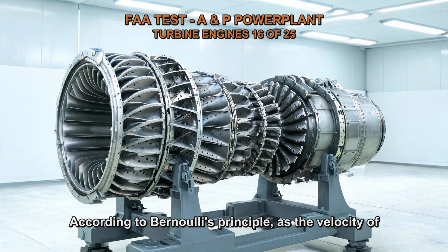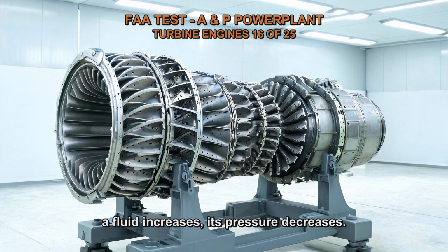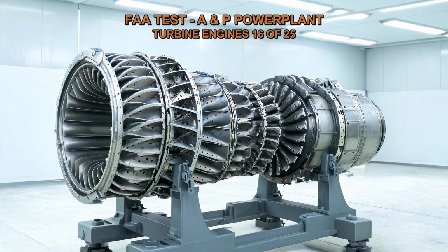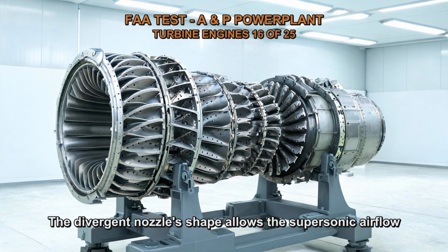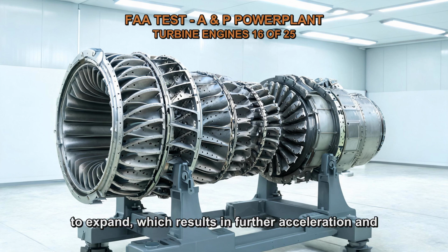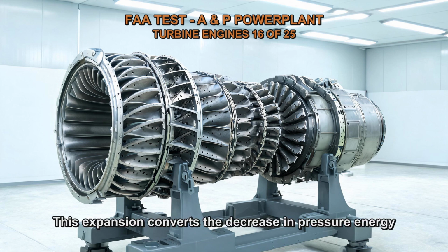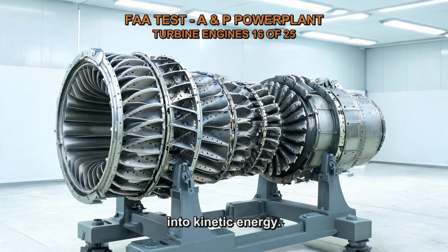According to Bernoulli's principle, as the velocity of a fluid increases, its pressure decreases. In a divergent nozzle, the velocity of the supersonic airflow increases, causing a corresponding decrease in pressure. The divergent nozzle shape allows the supersonic airflow to expand, which results in further acceleration and a decrease in pressure. This expansion converts the decrease in pressure energy into kinetic energy.